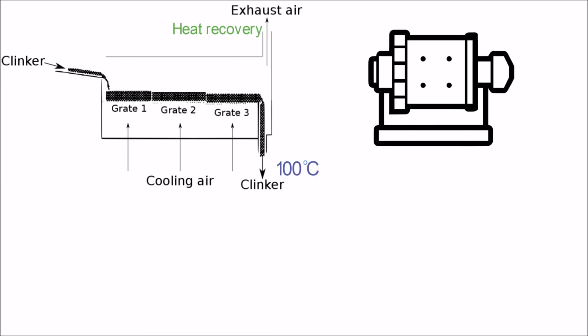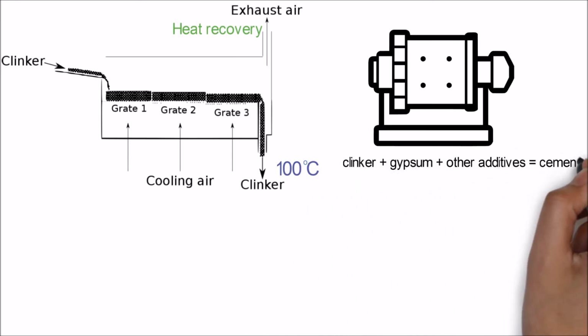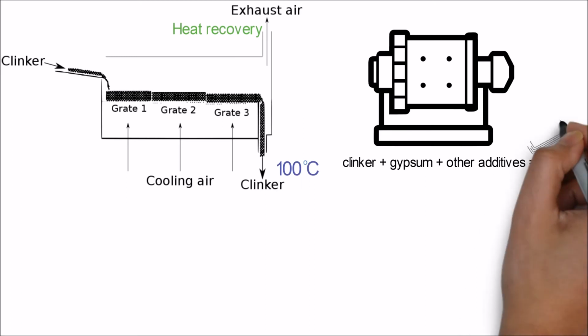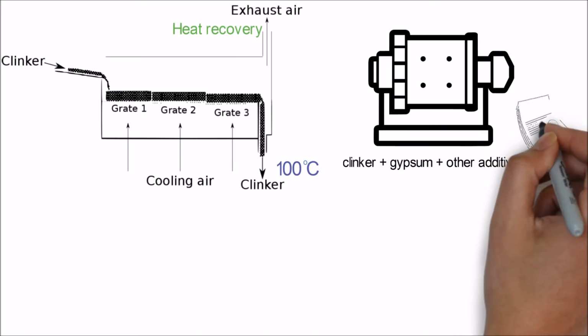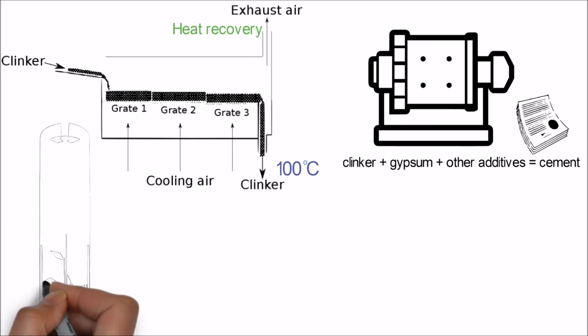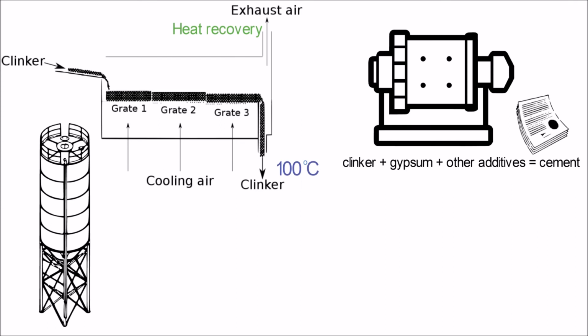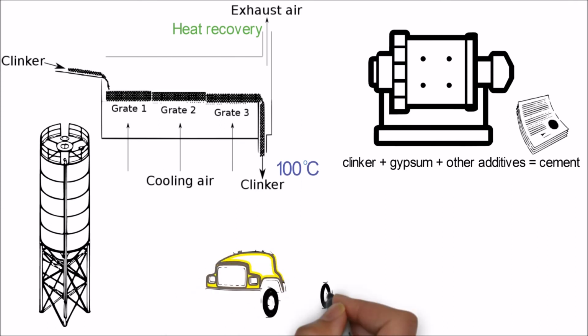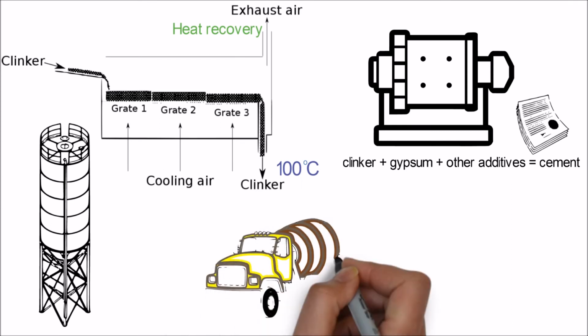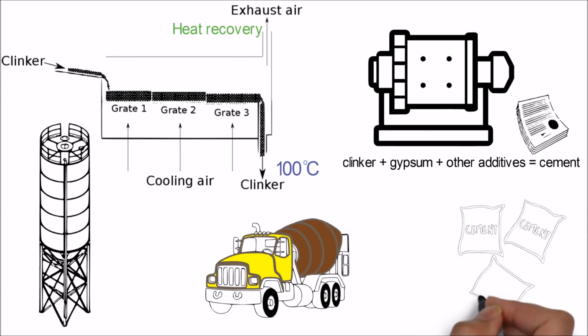Portland cement clinker is then ground in mills with gypsum for set control and/or other additives such as slag and limestone where appropriate for performance and permitted by specifications. The cement is then stored in silos or domes before dispatched to the market. In general, shipments of cement range from almost entirely bulk in developed countries to almost entirely sack in less developed countries.